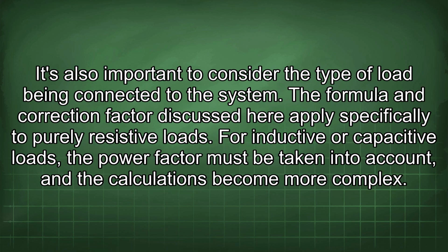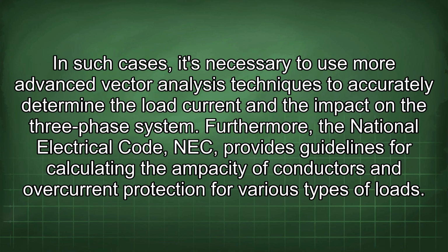It's also important to consider the type of load being connected to the system. The formula and correction factor discussed here apply specifically to purely resistive loads. For inductive or capacitive loads, the power factor must be taken into account, and the calculations become more complex. In such cases, it's necessary to use more advanced vector analysis techniques to accurately determine the load current and the impact on the three-phase system.